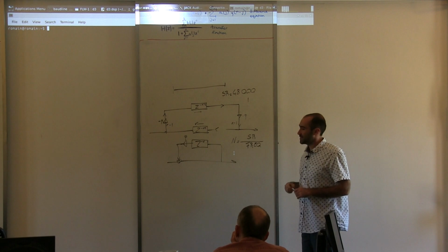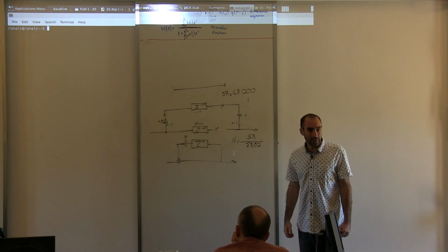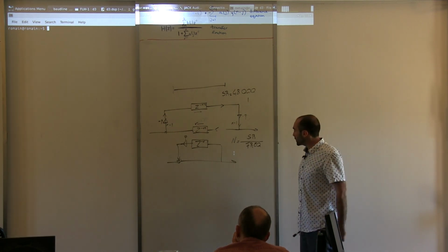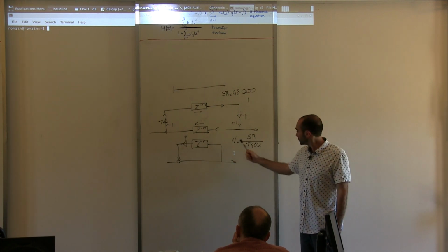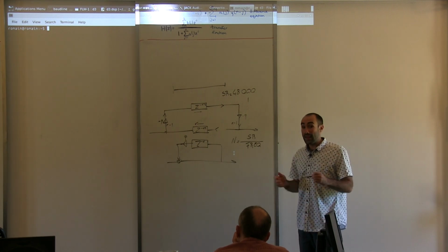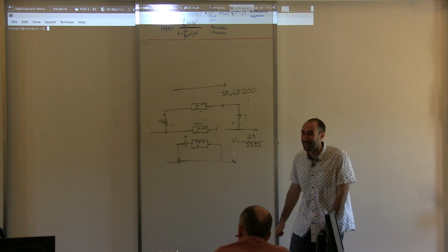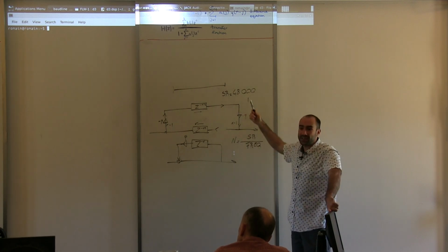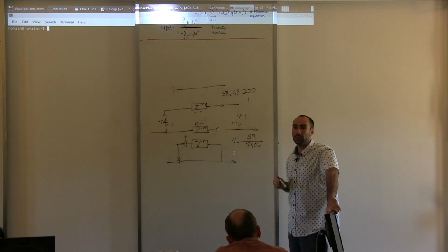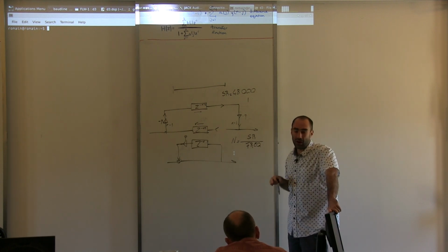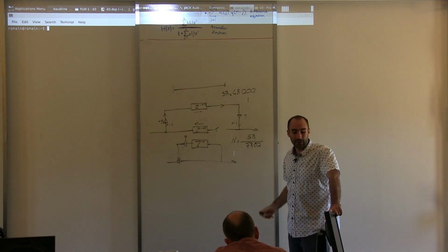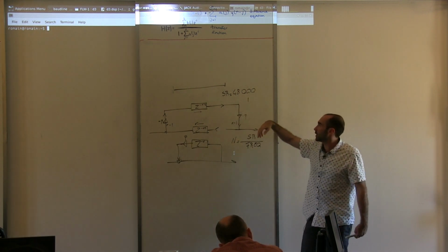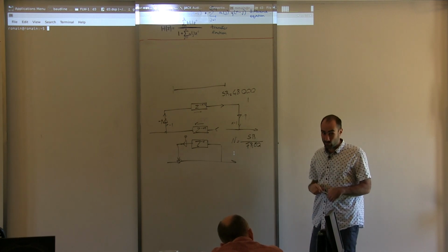So if we use a standard delay line, not a fractional delay line, not an interpolated delay line, what is going to be the problem with my string? Yes, it's going to be out of tune if I use high frequencies, depending on the sampling rate. If I have a very high sampling rate, it's probably going to be in tune in the human hearing range, and you're not really going to be able to make any difference. But if I have a sampling rate of like 44 kilohertz,